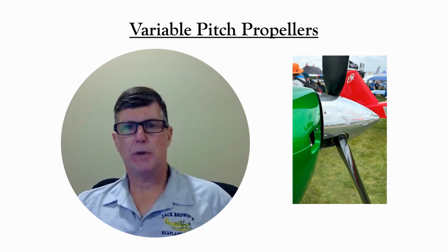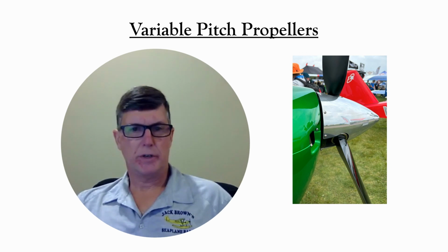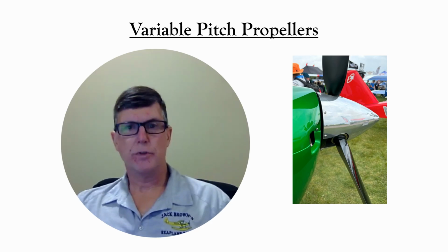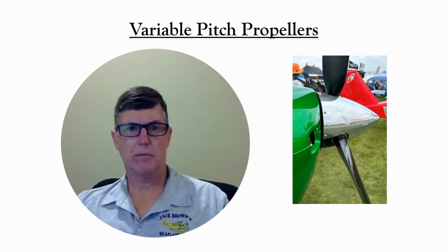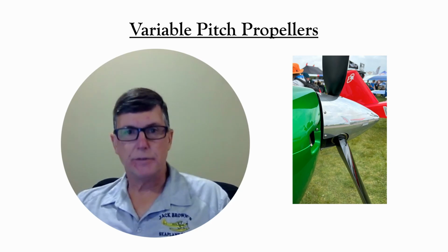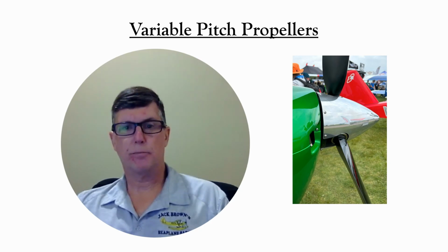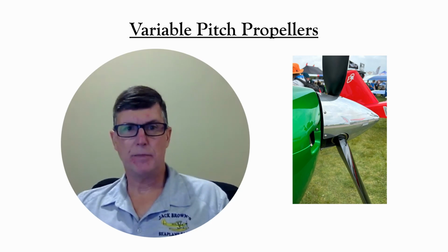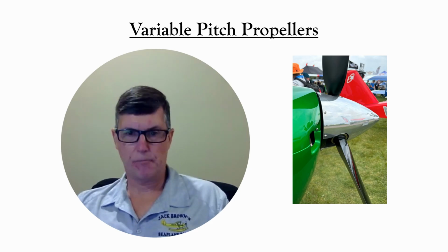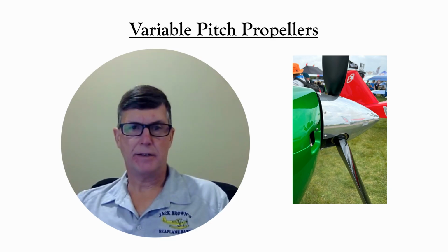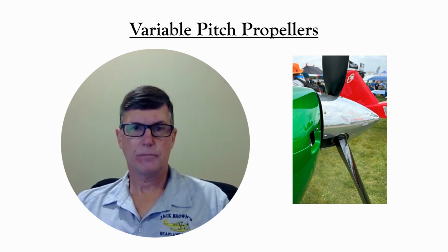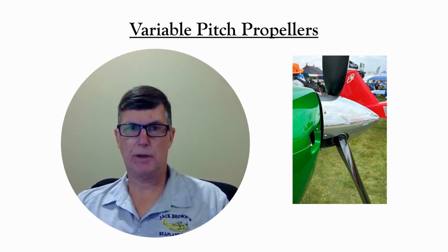In-flight adjustable propellers usually utilize hydraulic pressure, which is routed through the crankshaft to the propeller hub in order to change the pitch. The most common way that this gets controlled is a propeller knob in the cockpit that the pilot uses to set the engine speed. From that, a governor adjusts the pitch of the propeller to achieve that speed. That's called a constant speed propeller.